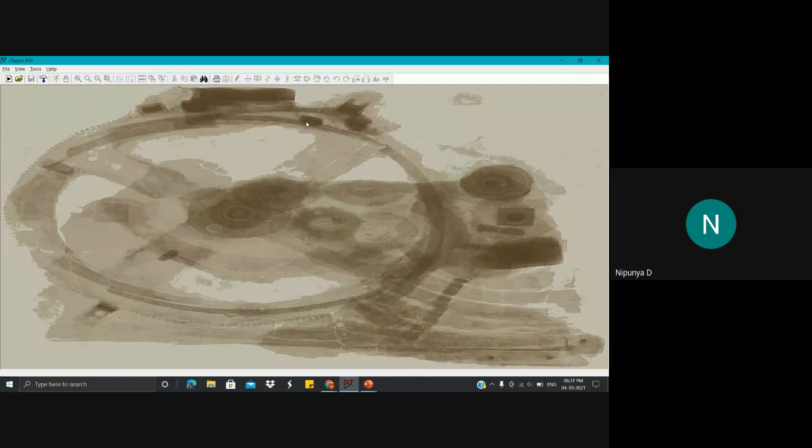So moving ahead, just open a new schematic, and we will be building a full wave rectifier. I hope that there are no doubts. For building a rectifier, we will require a transformer. LTspice doesn't directly offer a transformer, so we have to couple two inductors. So let's do that. And you can rotate it by pressing Ctrl R.